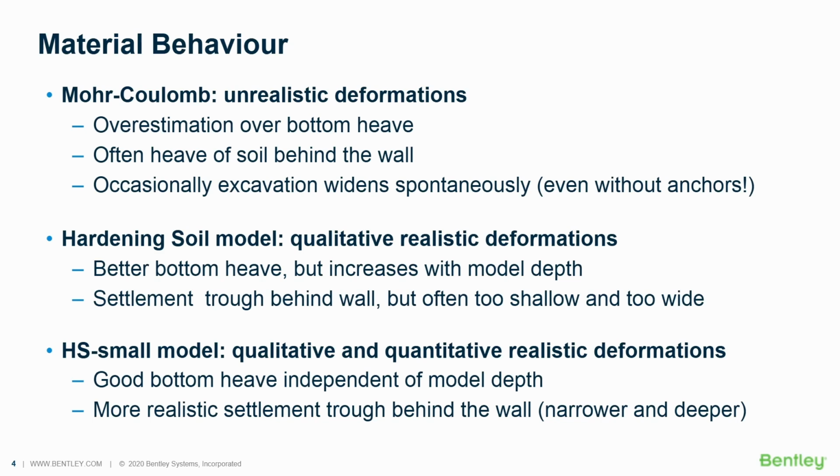And then finally, as I said before, the addition of the small strain stiffness dependency will also improve the displacements quantitatively. Of course, this will also require you to calibrate 2 additional model parameters compared to hardening soil. But this is usually our recommendation.